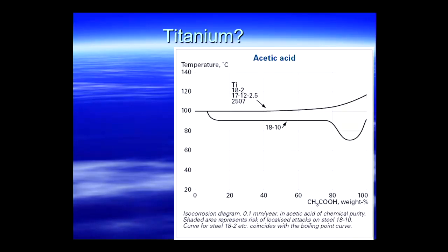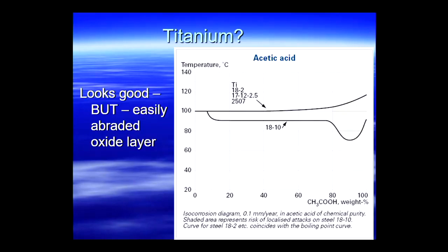You can see there's not a lot to choose between them. In any case, they operate at temperatures above that, what it's talking about there. So titanium's not much good. In any case, the oxide layer on titanium is better than stainless steel, but not much. So titanium probably would have lasted, instead of 6 months, probably 7 or 8 months, but that's it. What I wanted was something that would last 20 years. Same problem.